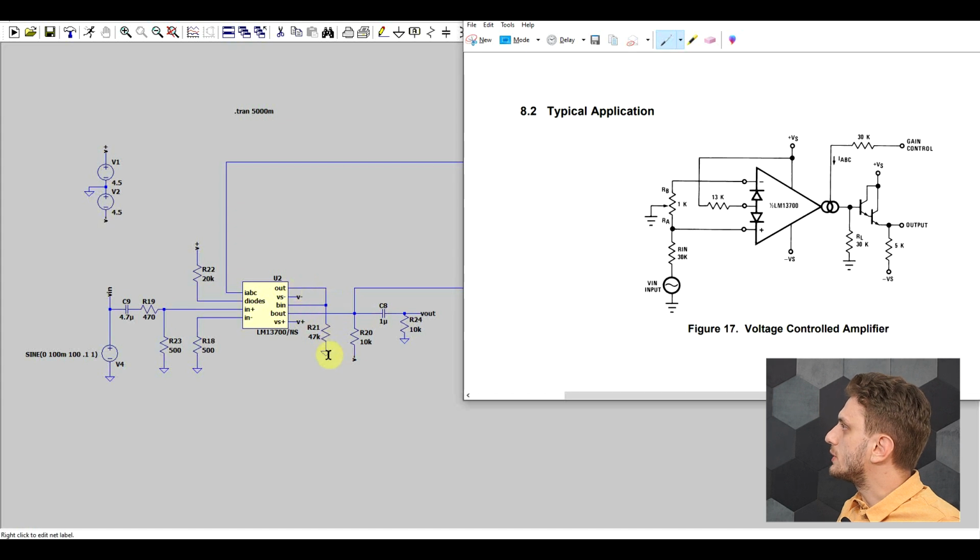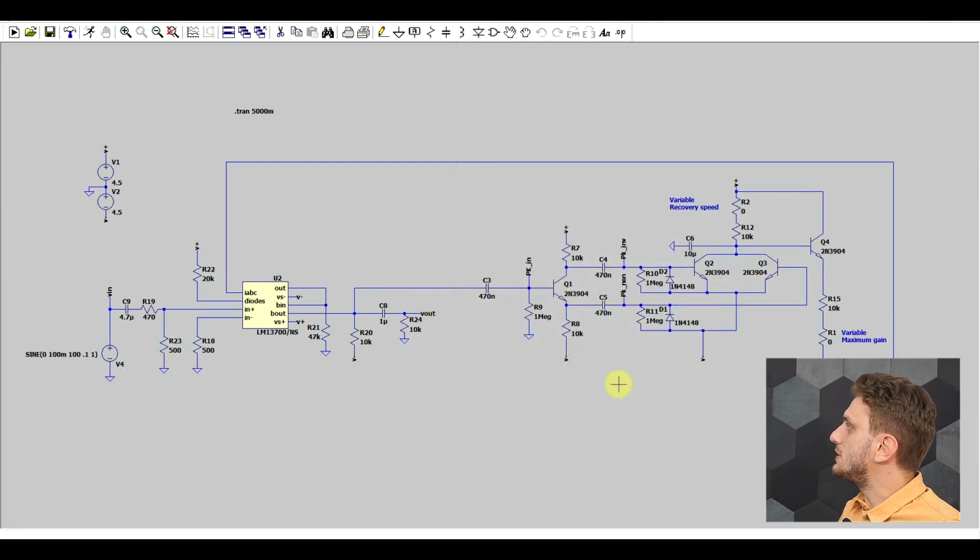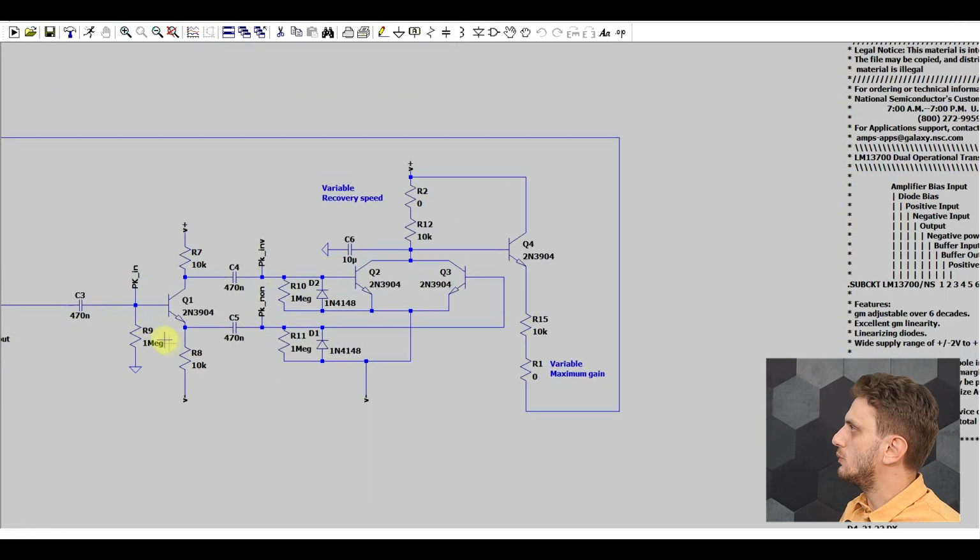And then we have our output connected to ground through a 47 kilo ohm resistor, and this feeds back into the buffer circuitry, so these two Darlington transistors, and then the output goes directly to the output, so this will couple into the second board, but it also feeds into this secondary circuit. What we have here, we have the first transistor that simply takes our input signal and provides a non-inverted and an inverted output, so the two signals are in phase opposition.